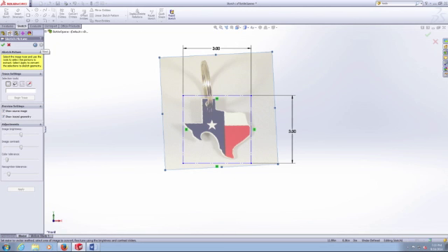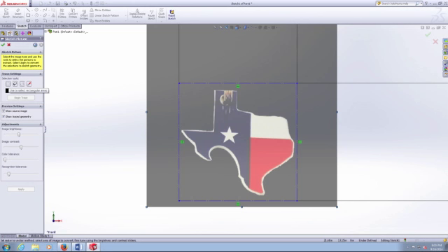On the Sketch Picture panel to the left, you'll see an arrow to navigate to the next panel. You'll find all the trace settings in that next panel. There are 4 different selection tools that you can choose from. Here I'll be using the rectangular selection tool and selecting everything inside the box I drew earlier. Once you've made your selection, you can press the Begin Trace button.